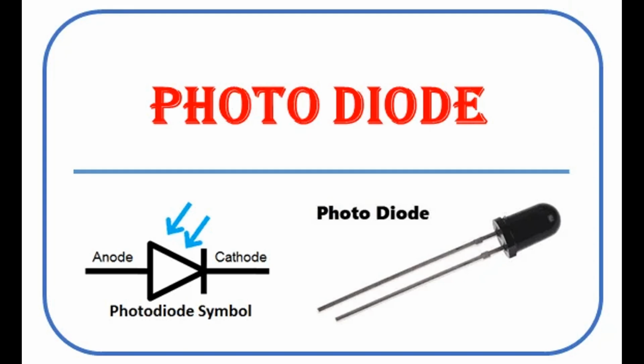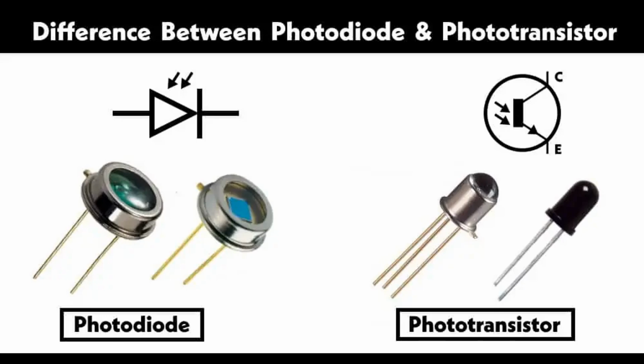7. Capacitance. Definition. The photodiode's capacitance is the ability to store charge in the depletion region. Influence on response. Higher capacitance slows down the photodiode's response, reducing the speed of detection. Reverse bias. Applying a reverse bias reduces the capacitance, improving the speed and allowing for operation at higher frequencies.